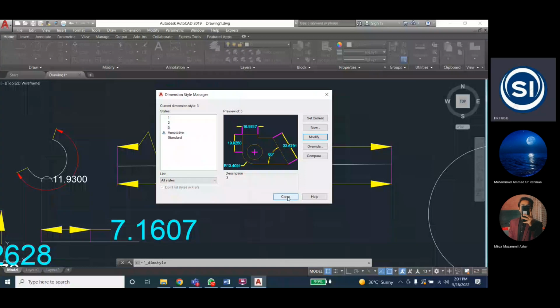Tail of the dimensions, the tails between the text and the tails of the dimension line. This is actually there. Again, you can apply and see the difference. Okay, modify. Again, not 10, by default. Default value. What was the default value? 0.09. Now the text alignment, that is horizontal. Now the one aligned with the dimension line.